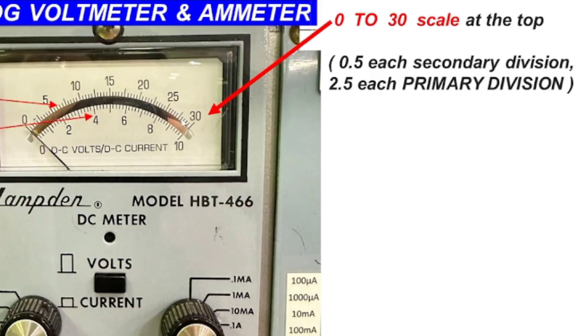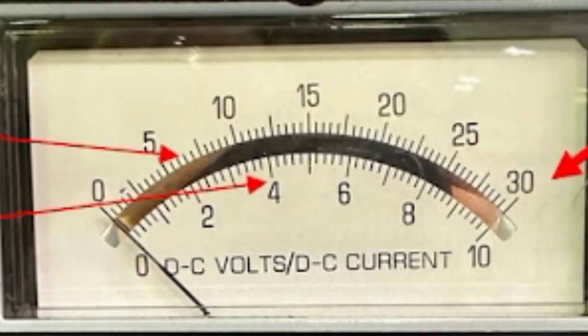Now at the top, you will also see the secondary division, which represents 0.5 for each. Therefore, the small lines at the top of the scale represent the 0.5 value, and the big lines here represent 2.5. Therefore, this long line here is 2.5.